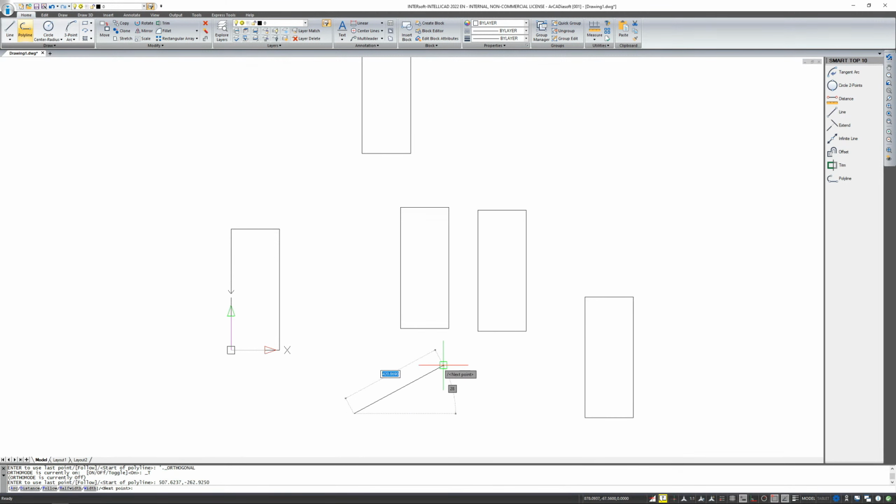And when I approach the 45-degree angle, I stop the cursor on this line and I can type 200. And if I want to draw the same rectangle only inclined, I do not have to give angles. I just use these additional polar lines, which will allow me to draw these elements in a simple way, determining only their length.